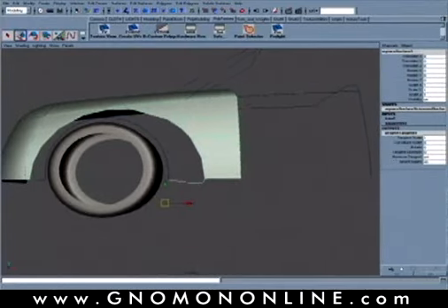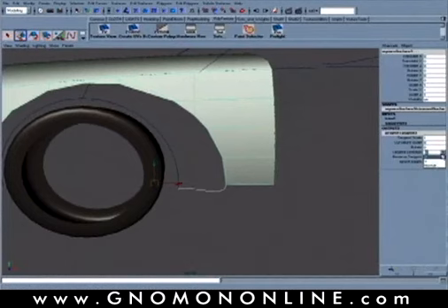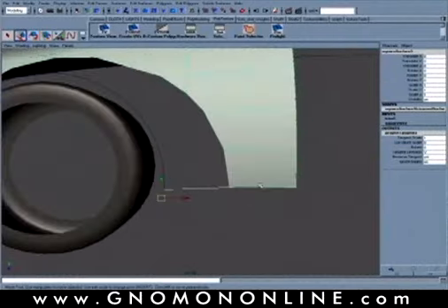So I can go in the attribute editor or into the channel box here, give us a little more room, and you can see that it says in the channel box tangent direction. That's set up to U. So I'm going to change the tangent direction to, in this case, run in the V direction of the surface.